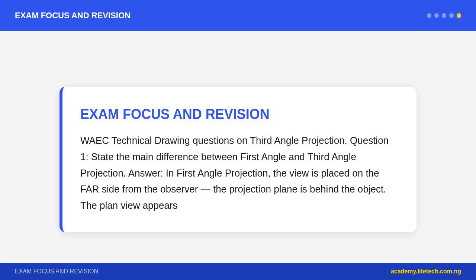First angle and third angle are both correct, they are simply different conventions, like driving on the left, Nigeria, UK, versus the right, USA, France. Both get you to the destination correctly, as long as everyone follows the same convention. The symbol in the title block is the rule of the road for every technical drawing.